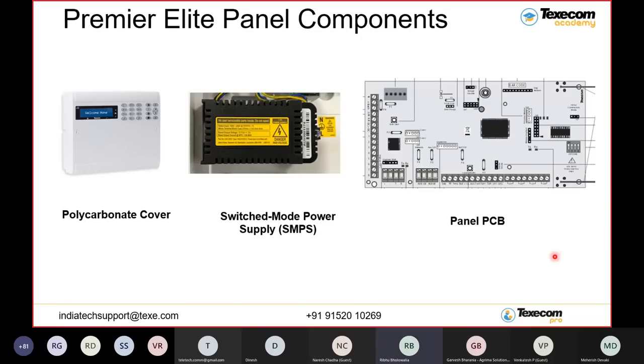This is very important when you are doing wireless installations. Once all the programming is complete, and specifically I'm talking about the enrolling of the sensors, okay, this is called the enrolling of the sensors. Once all the enrolling of the sensors is complete, then power off your control panel and start mounting the devices.